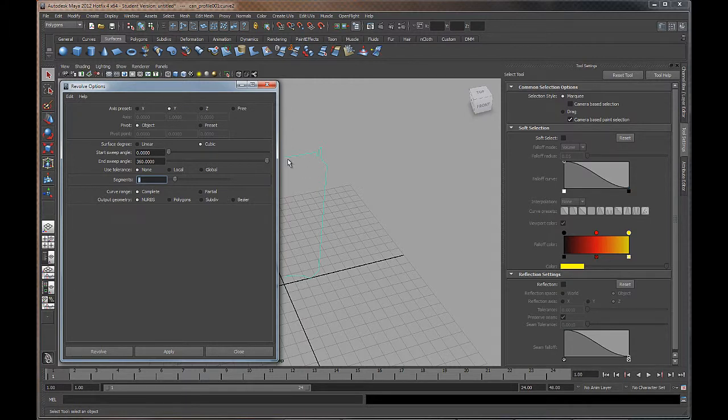So if you think of maybe a trampoline, think about the steel frame or the aluminium frame on a trampoline. Think of that as being this curve. Now the mat of the trampoline, which is stretched out inside the frame, that's kind of what the NURBS surface is. It's sort of that rubbery kind of panel in the middle. All right. So that's sort of what it is. It's a calculated stretchy surface over a set of curves. All right, so I'm just going to leave this here and I'll hit Revolve.